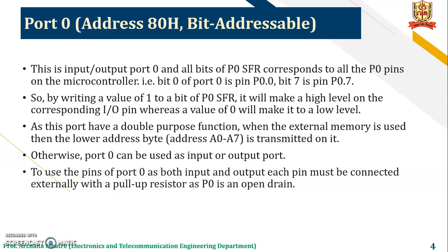As this port has a dual purpose function, when the external memory is used, the lower address byte, that is address A0 to A7, is transmitted on it. This we have studied in the pin diagram of the 8051 microcontroller. Otherwise, port 0 can be used as an input-output port. To use the pins of port 0 as both input and output, each pin must be connected externally with a pull-up resistor, as P0 is an open drain.